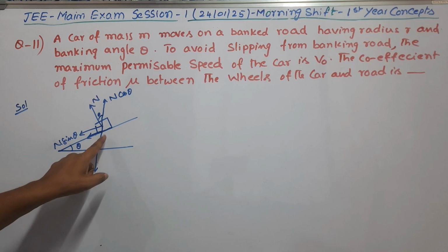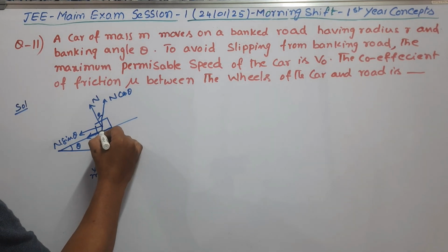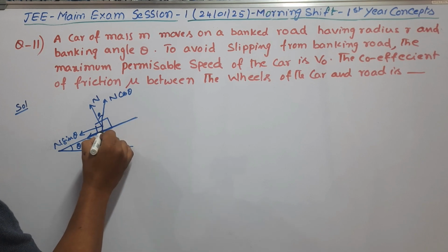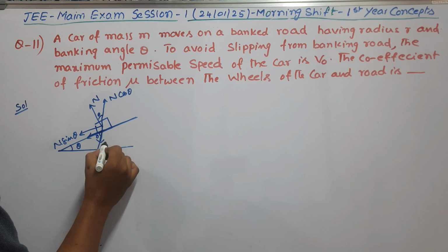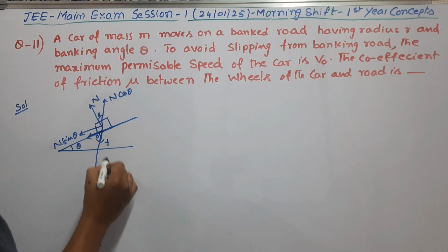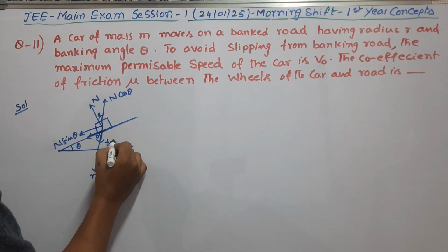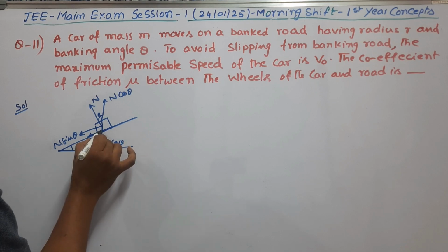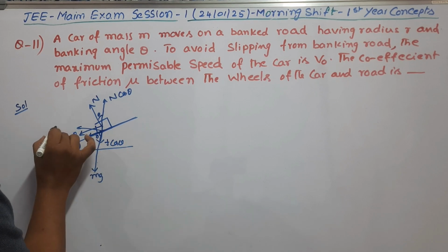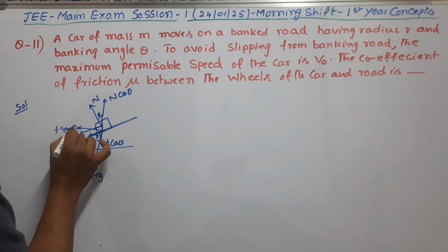The friction is also resolved into two components. This is the angle theta, so the adjacent side is the frictional force F cos theta. One component acts along this way, and this one is F sin theta.